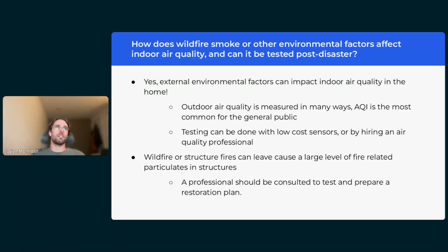It's not a constant water issue, but maybe every 3 weeks enough water gets in and gets wet for a day or two and then dries. It's possible if I took an air sample here, I would detect an elevated level of mold, and I don't see any visual clues. And it could be detecting that hidden mold issue.